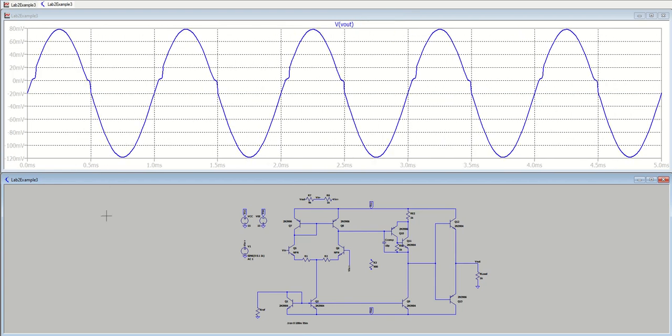So I'll run the signal, and notice that the DC component that we were measuring when we had them both set to ground was negative 18.9 millivolts. And so that is right around where we're measuring for the starting point of our sinusoid.